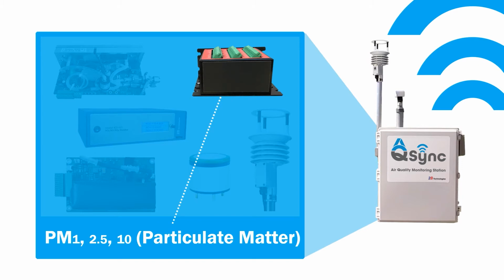We use the MET1 AQ mass profiler for particulate measurements. The AQ mass profiler is an optical particle counter that detects single particles between 0.3 and 10 microns in diameter. Aerosols are sampled into the profiler through a total suspended particulates inlet, which is heated during periods of high humidity.